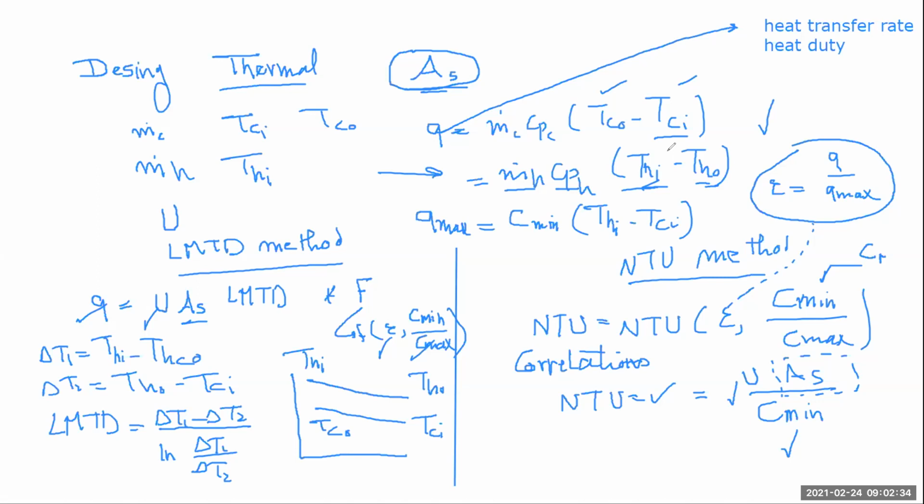Nice, Doctor. About the fluids, what type of fluids do we use? Do we use just water, or are there special ones? Water and air are the cheapest and the most abundant fluids. But sometimes, suppose that you need to have a solar collector system, and you need to install it in Tabuk this week. You cannot put water in the solar collector, because if the temperature went below freezing, water will freeze in the tubes. So it's not an option there.